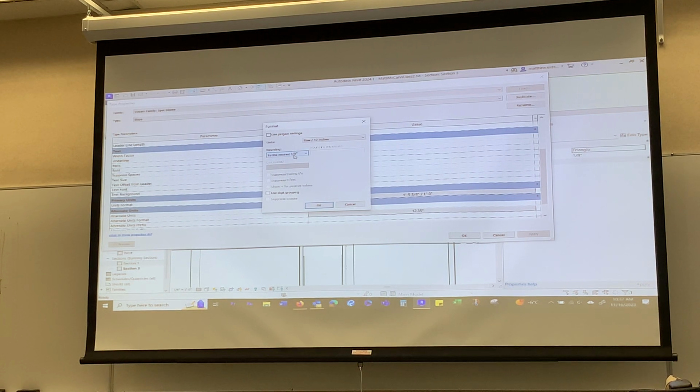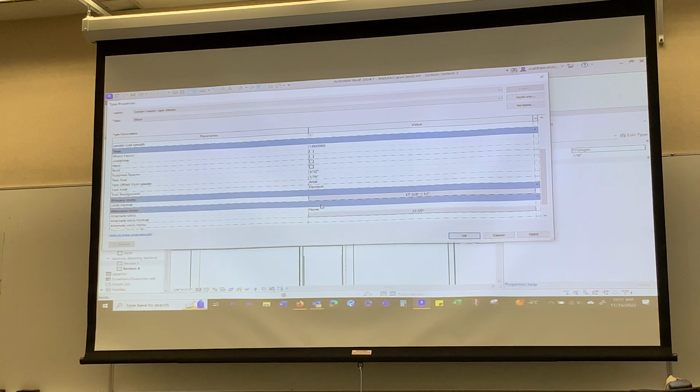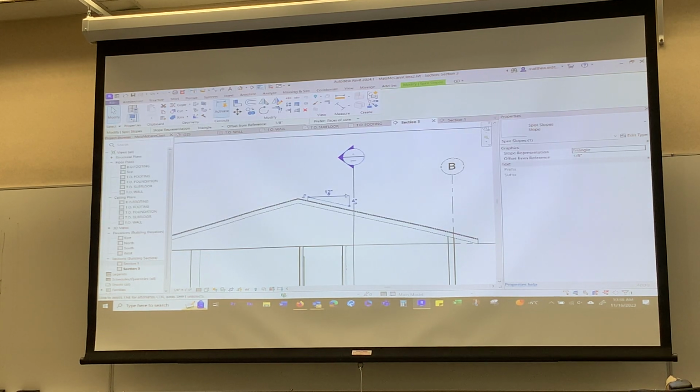Rounding, if you've got oddball, you can change that, right? Sometimes you get these, 5 and 3/8, depending on the truss design. You can get different pitches that are a little bit gnarly. Then you can express it in degrees too if you want. Sometimes framers like that, but most framers know it's right on your speed square. There's a conversion right on there, but it's 18 and something, 4 and 12. Okay, so now it's 12 inches and 4.